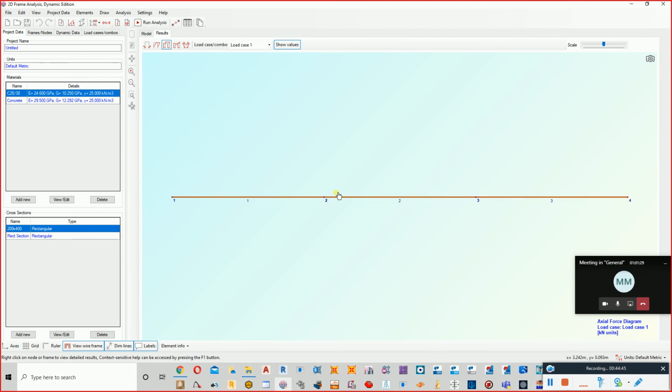When we have the loading perpendicular to the cross section, this is flexural, the element is bending. When the element's major axis and the loading are acting in the same line, then this is going to be considered axial loading. A good example of an axial member or axial loading is a column. You can see the load for the column is coming on the same major line. So this is my column. It has a major axis and it has a minor axis. So the load is coming on the same line of the major axis.